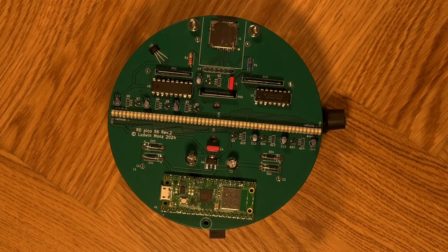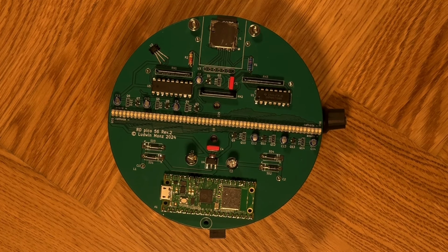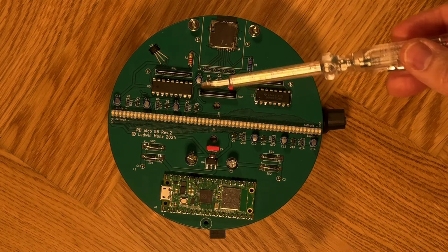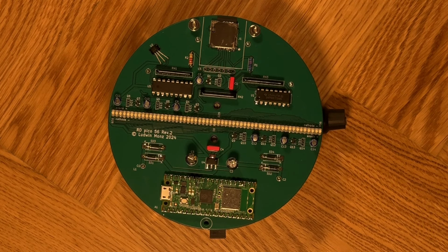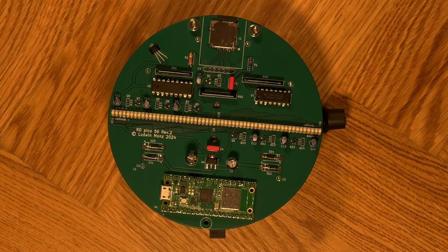While I used serial shift registers to address the LEDs in the previous models of the display, I use a different method in this version, namely multiplexing. The circuit consists of very few parts, 2 integrated circuits and some MOSFETs. The multiplexing method was the main challenge of this new model, as it has to be very fast. It benefits from the programmable I/O of the RP2040 microprocessor, as I will show later.